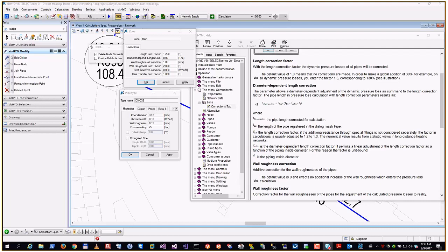He said that he adjusted the heat losses for the network, and once the temperatures were okay, he had a very good synchronization between model results and the reality. But the key to it was heat losses, and not roughness and length correction. First heat losses, and if that matches, then the rest follows. But that is a user who is doing the design and the operations, and he knows all the people operating the plants, so he's in a very good position to get all the data.